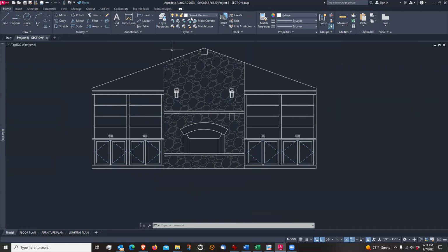So I'm on my line weight medium. For right now, I'm going to draw all of my lines on the medium line weight. And I believe all of these lines are drawn on medium line weight. And the truth of the matter is that later on, when we're drawing the sections, the cut through the ceilings and the roof and the walls and the floor, those are the heavier lines, and all of this stuff is going to go on a lighter line weight.